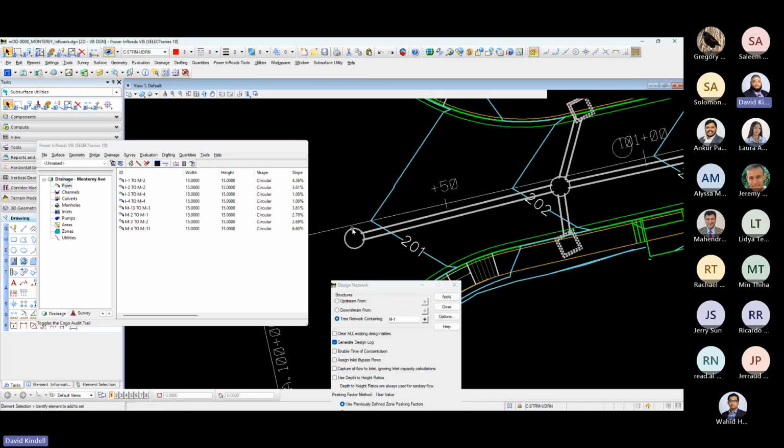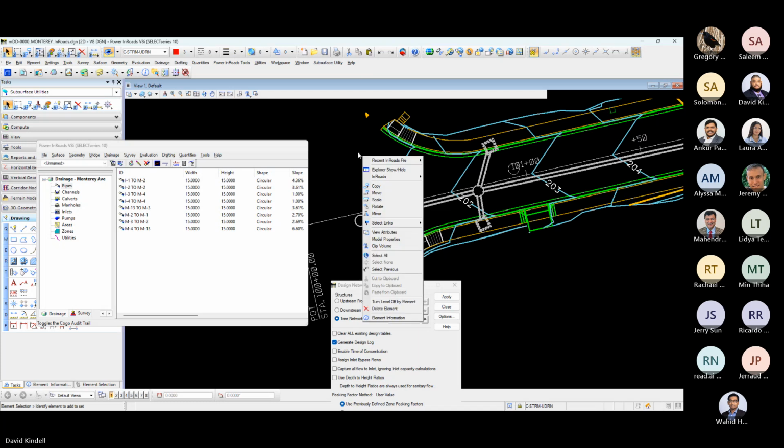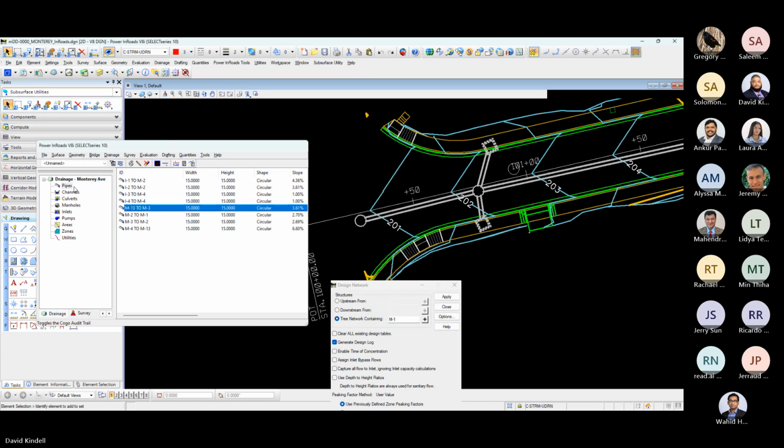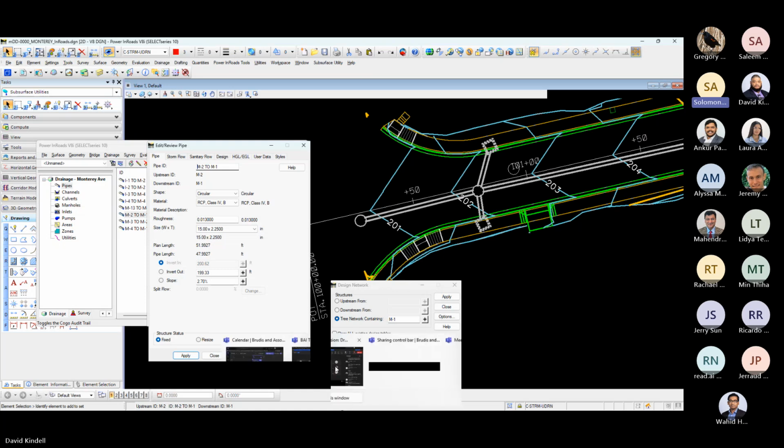Okay. So this is Manhole 1, right? The pipe from manhole 1 to manhole 2. Inlet 1. Manhole 1 to manhole 2. The other invert. So you see the invert here, okay? I thought that invert 199.33 is going to be invert in because the pipe is coming into that manhole.